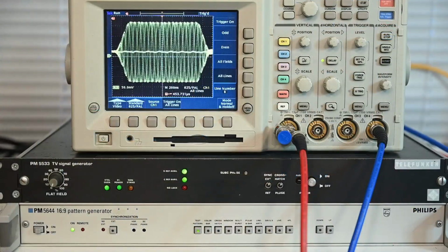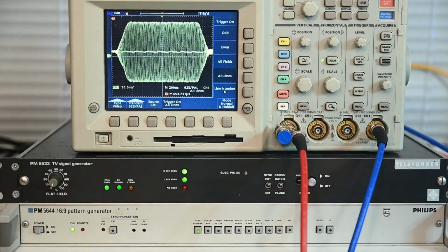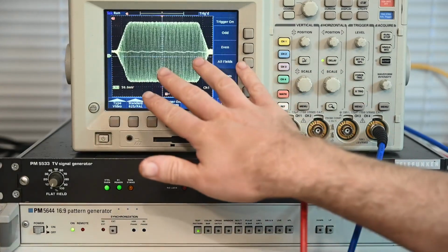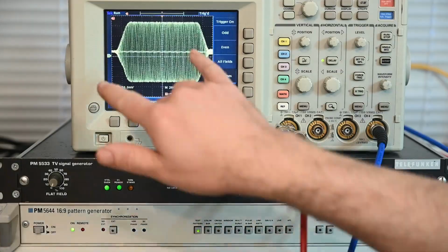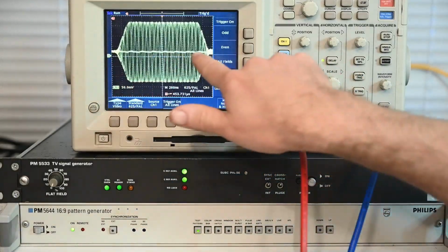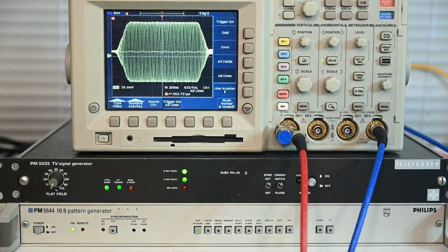Now next up, a bit more about that relationship between the color subcarrier and the horizontal drive. I could just throw a bunch of equations at you and say, well, you've been told, but I prefer a more practical explanation. If we have a look at the color burst here and just trigger on a horizontal sync pulse for every single line, what we see is just this envelope of a signal, and we're seeing the phase of the color subcarrier at hundreds or even thousands of different rotations, and it looks a bit random, like there's no relationship at all.